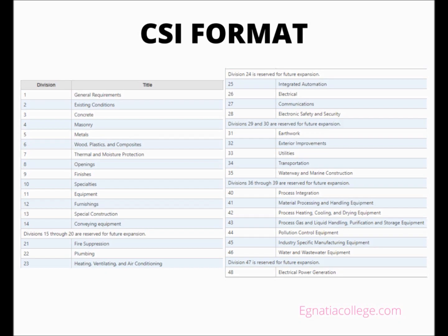While this format makes organization of large projects easier to follow, it would be very cumbersome for a small project, like a single-family home. A more practical and often used system is to partially follow the CSI format. The major divisions follow the CSI format. The numbering of subsections is modified or dropped altogether.